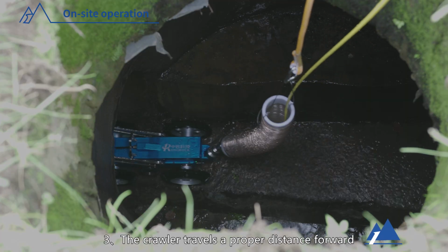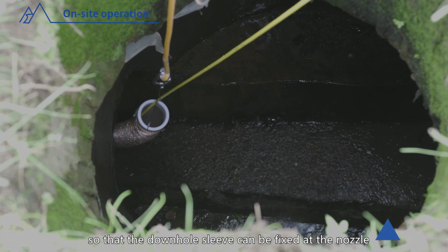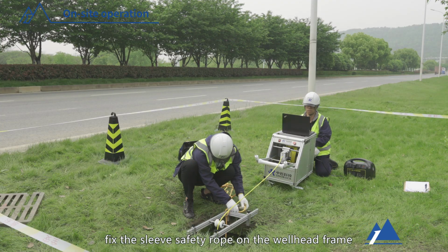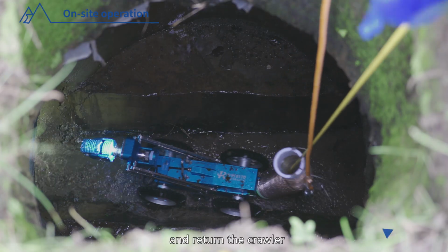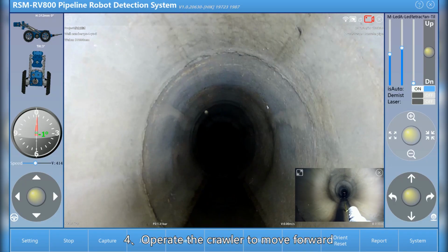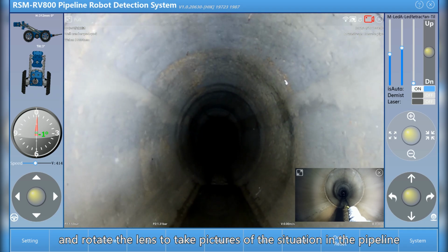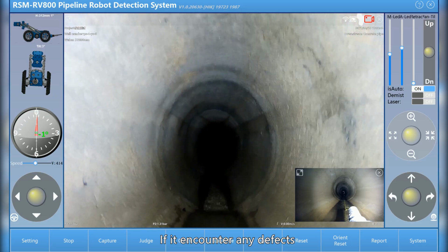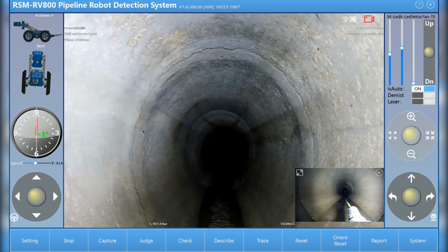3. The crawler travels a proper distance forward so that the downhole sleeve can be fixed at the nozzle. Fix the wellhead frame at the wellhead, fix the sleeve safety rope on the wellhead frame, and return the crawler to the position of the pipe mouth to start testing. 4. Operate the crawler to move forward and rotate the lens to take pictures of the situation in the pipeline. If it encounters any defects, you can take a screenshot and judge the defect in time.